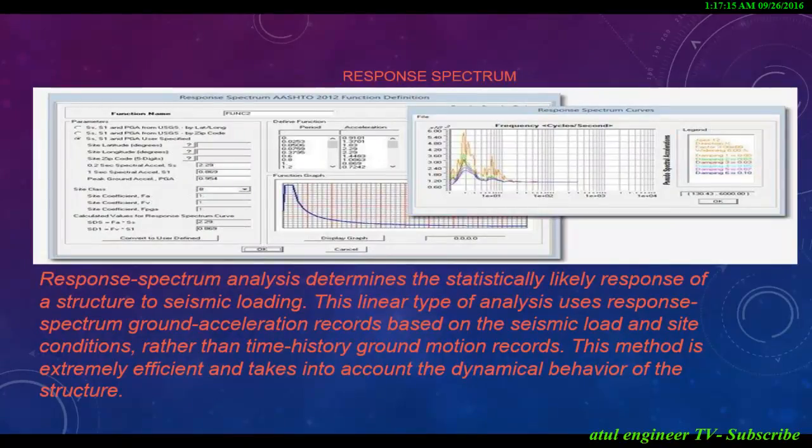Ritz vector modal analysis finds the optimum modes for capturing structural behavior in response spectrum and modal time history load cases, and is more efficient for this purpose than eigenvector analysis.